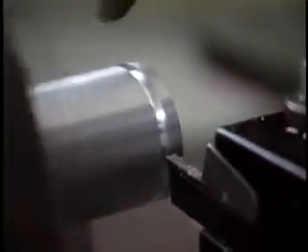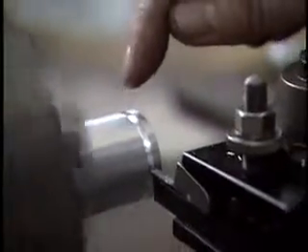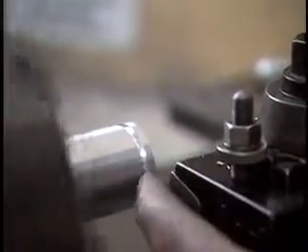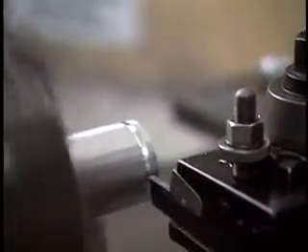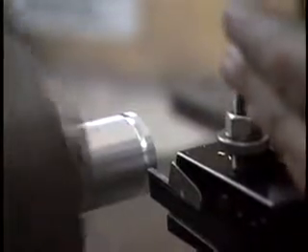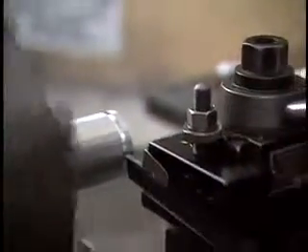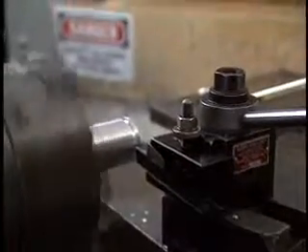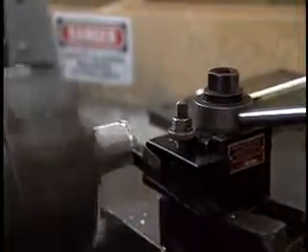It's reasonable to cut a groove of about this depth dry. Cutting any deeper puts more and more of the edge of the tool into contact with the sides of the groove, generating heat. So as you go deeper into the part, it's more and more important to use some cutting fluid.